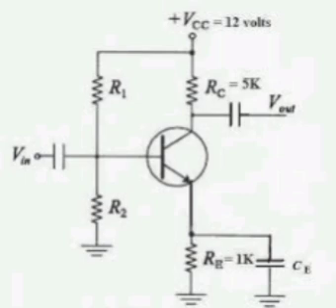So ERFC of x equal to 1 minus ERF of x. That equals 3 into 0.3 into 10 power minus 4 equal to 1 minus ERF of 10 power minus 6 whole by root over 4 into 10 power minus 17 into t. ERF inverse of 0.9999697 equal to 10 power minus 6 whole by root over 4 into 10 power minus 17 into t.